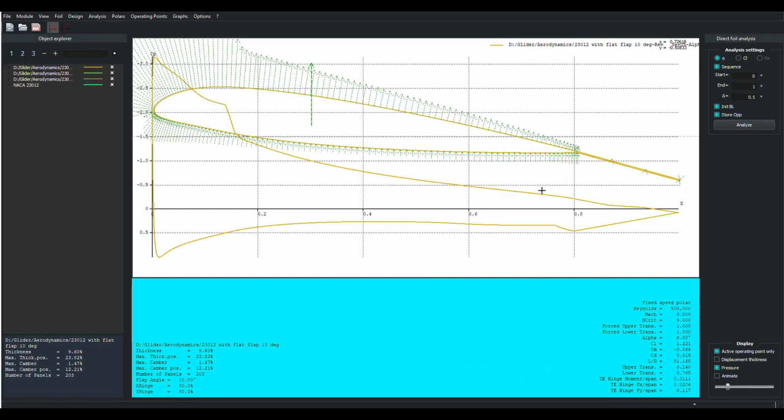Okay, I wanted to take a moment here and show you one other flap deflection for this type of control surface, the flat plate. That is 10 degrees. And I find it to be fascinating. First of all, the program can actually handle doing the calculations for this funky airfoil when the flap isn't deflected as much. And you'll see that at 10 degrees of deflection, there's no adverse pressure gradient barrier here. It's very easy for the flow to just continue on its way. In fact, I'm going to turn off the pressure indicators here.